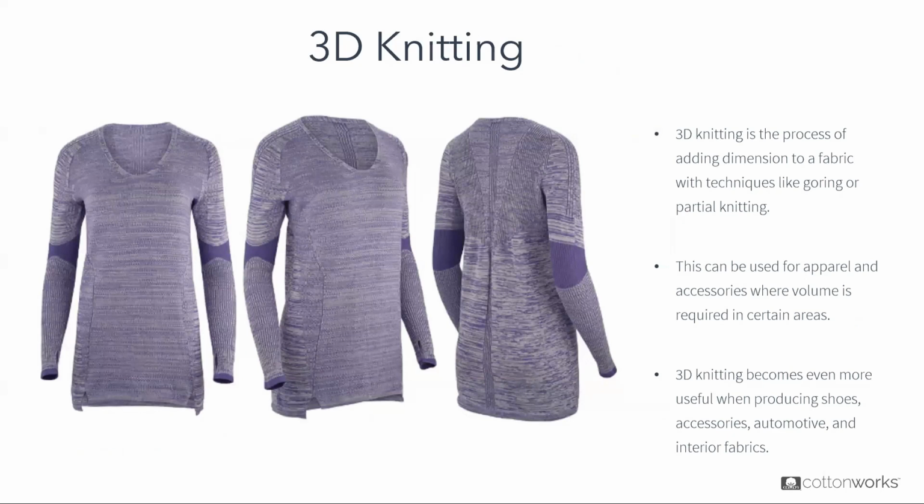3D knitting differs slightly from integral knitting because we are adding that extra dimension. A good example of this is on the sleeves of this sweater, where you can see certain parts have more rows than others. We achieve this by partial knitting or short rowing, sometimes also called goring or flechage. And this is where the carriage moves back and forth along certain areas rather than just knitting in a straight tube. This is great for garments as it allows a better fit, but really comes into its own when we are knitting accessories or shoes, automotive products, and interior fabrics such as covering furniture.